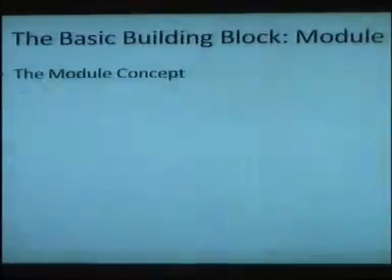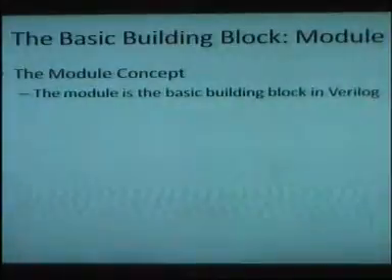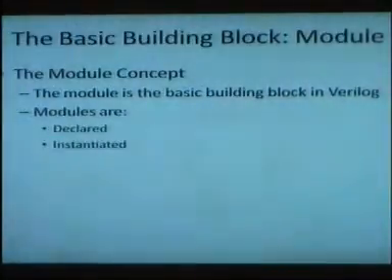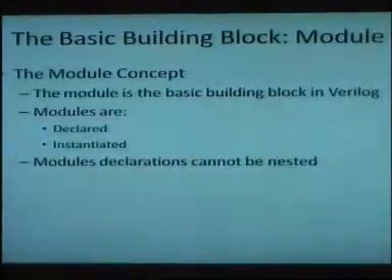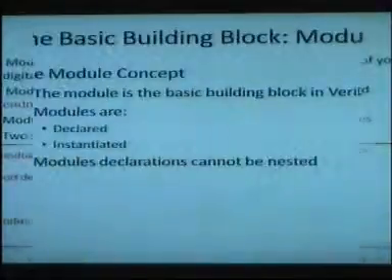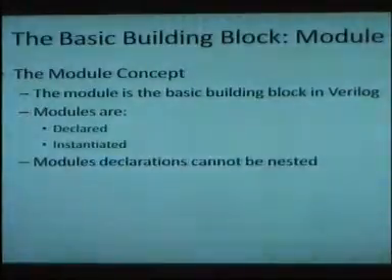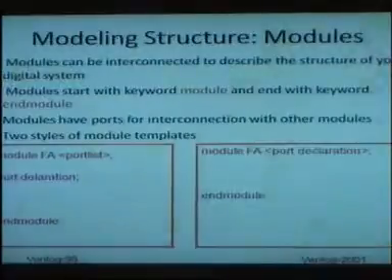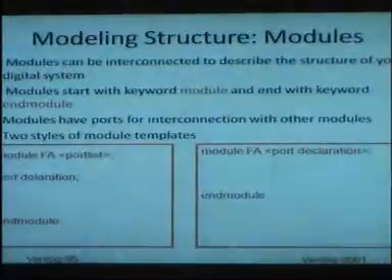While you are designing on the drawing board, you make these boxes, and each box is defined in a module. So the basic building block is a module. You declare modules and you instantiate them, and in Verilog you cannot nest module declarations. I mean, inside a module you cannot define another module. In SystemVerilog you can do that. In a module you can instantiate other modules, but you cannot declare another module.